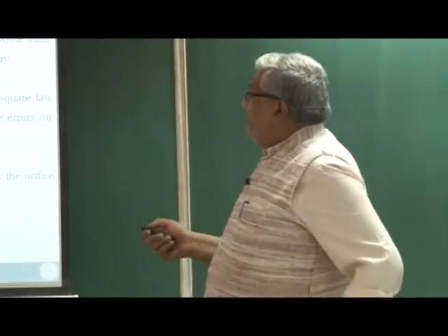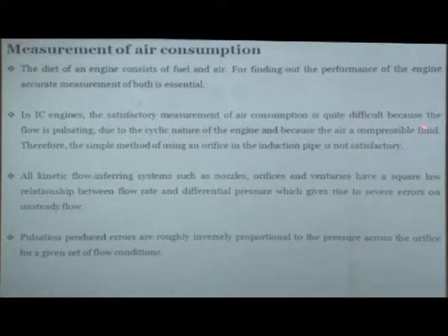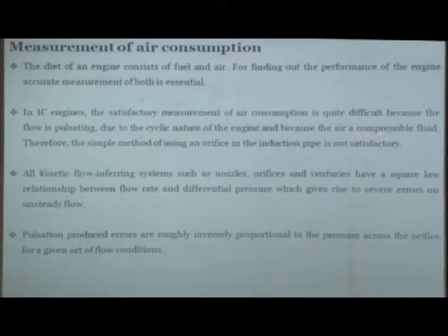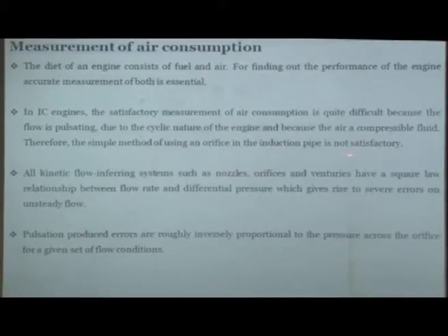So, in IC engine application, satisfactory measurement of air consumption is extremely difficult, because the flow is pulsating due to the cyclic nature of the engine, and because air is a compressible fluid, that also, okay. Therefore, the simple method of using an orifice in the induction pipe is not going to give you a satisfactory result. In fact, the manometer will all the time keep on dancing, it will not get enough time to stabilize, right, because of the pulsating nature.